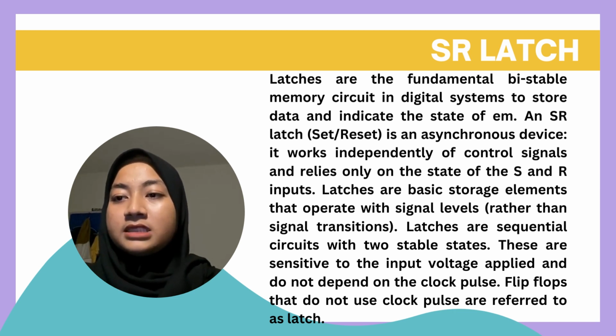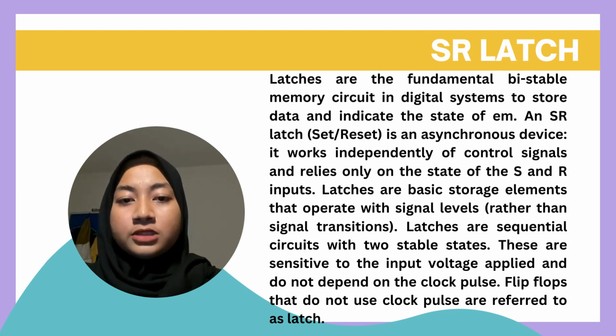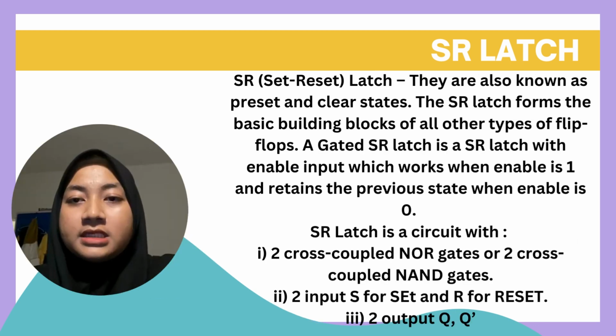Latches are basic storage elements that operate with signal levels rather than signal transitions. Latches are sequential circuits with two stable states. These are sensitive to the input voltage applied and do not depend on the clock pulse. Flip-flops that do not use a clock pulse are referred to as latches. Okay, so what is an SR latch?